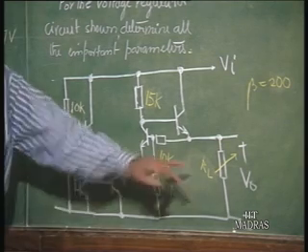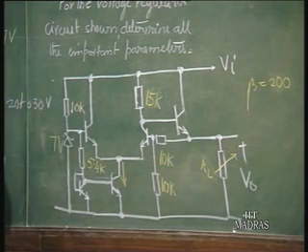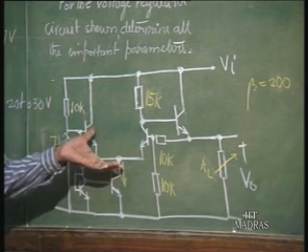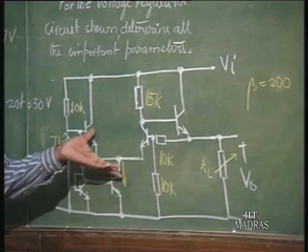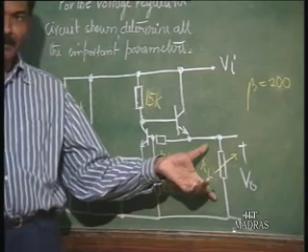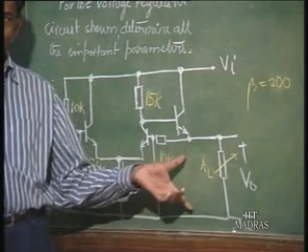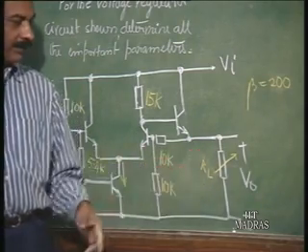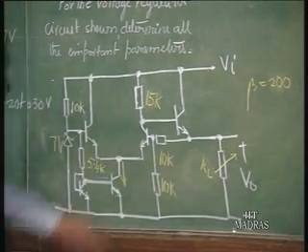And let us say RL, we would like to now know how much current I can draw before this circuit starts failing, stops functioning as a voltage regulator. First of all, is there a minimum current, is there a maximum current, etc. So, the current drawn here is V naught by RL.